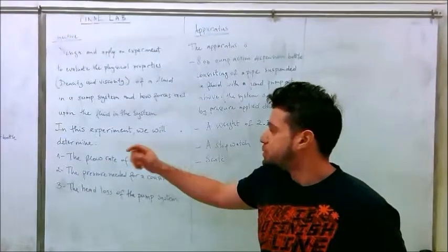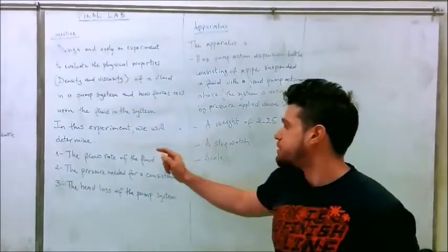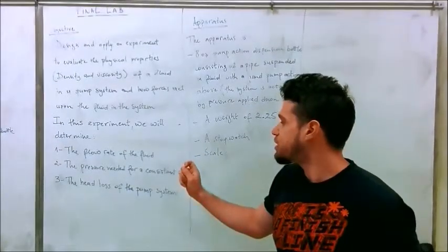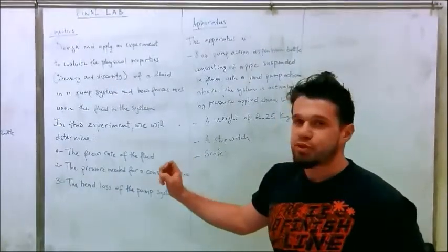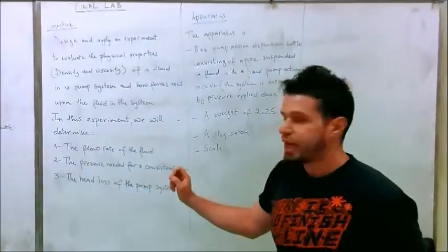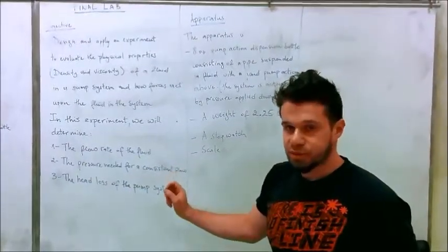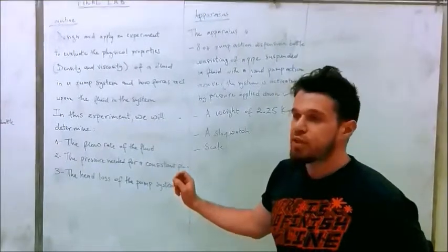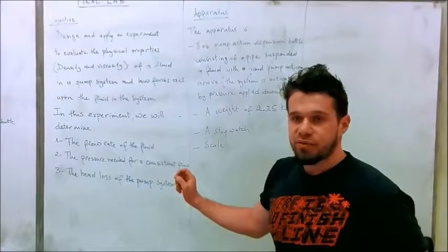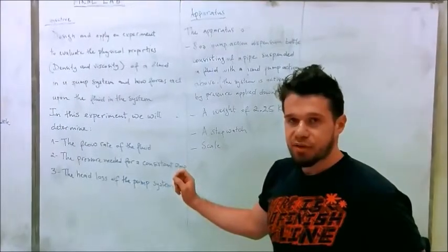In this experiment, we will determine the following. 1, the flow rate of the fluid. 2, the pressure needed to produce a consistent flow rate. 3, the head loss of the pump system which the fluid travels. These will also be evaluated with the Fluent program for accuracy.